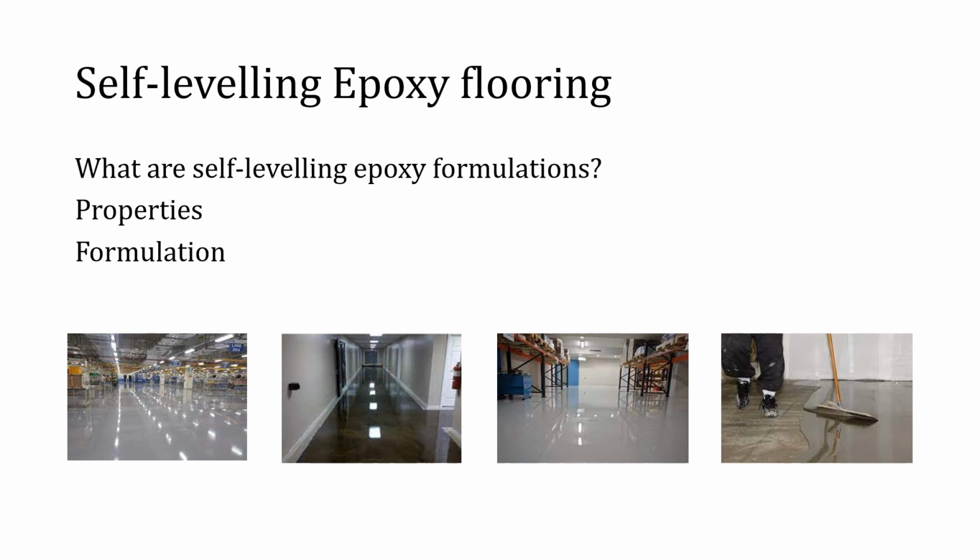Self-leveling epoxy formulations are fast-cure systems and are designed to result in a dense, impervious, and seamless surface. These features result in an easy, clean, hygienic floor required in hospitals, food processing plants, laboratories, pharmaceutical manufacturing areas, meat packing plants, etc. For self-leveling epoxy floors, often bisphenol A or bisphenol F resins are employed as the base resins. And in the formulation, curatives, diluents, a mixture of silica flour and silica sands, and special additives such as anti-foaming agents are employed.